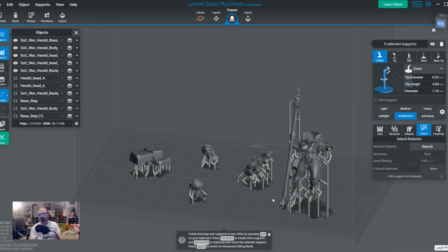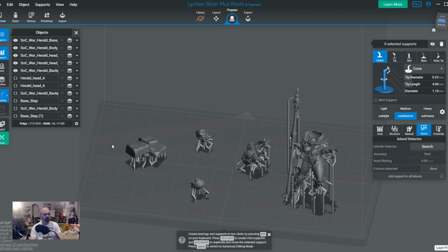More times you've got to worry about suction when you're working with parts that are hollow, because you have to put the holes in. But a lot of times I've seen people forget to either put holes in, or they don't put holes in the right place at the bottom, and they can't drain or air vent quickly enough. And that creates enough of an issue and a vacuum where it can pop that free, and then that's it. The rest of the print's not happening. So you've got to be careful with your hollowing, because not all types of hollowing or methods of hollowing are created equal. So you do have to keep that in mind.